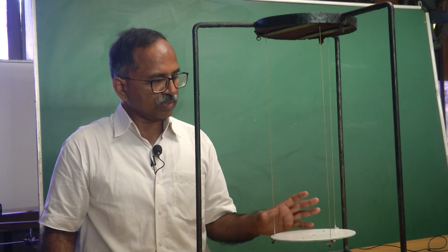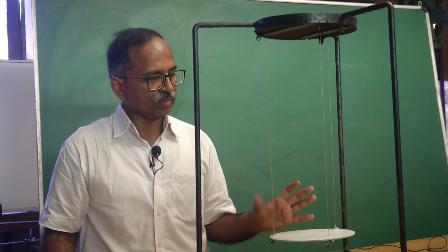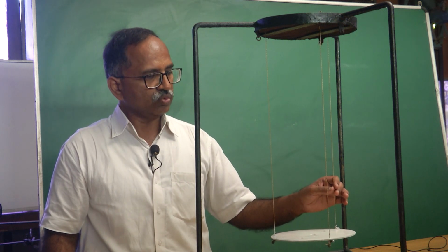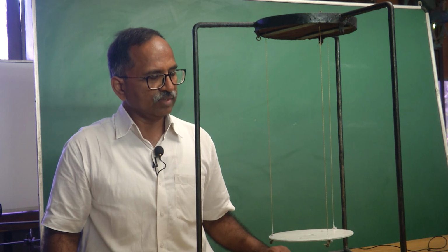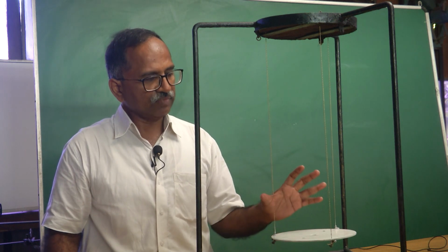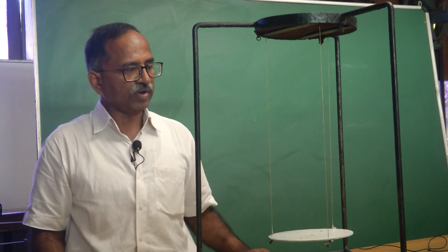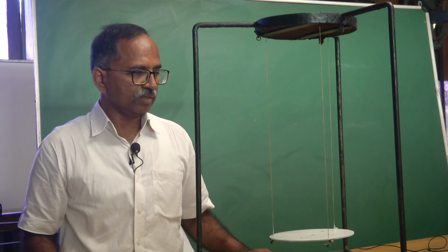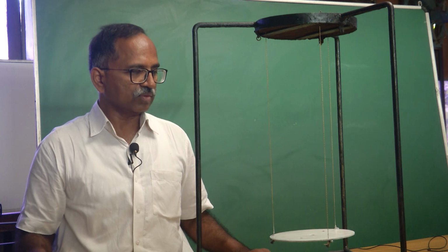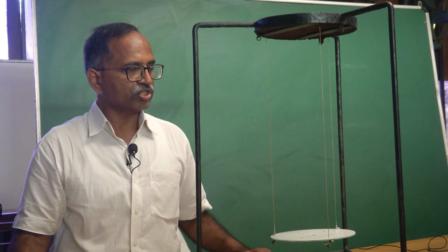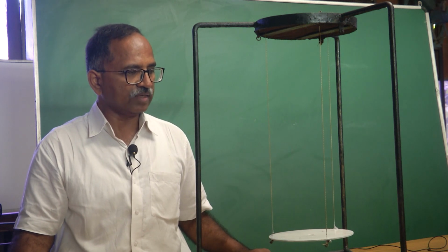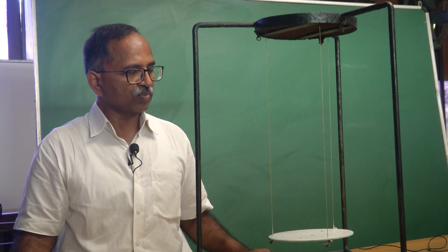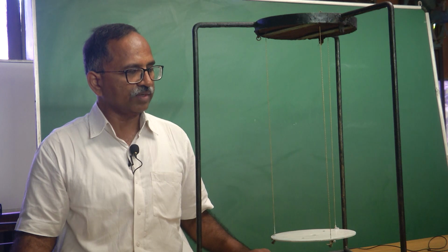Now, what is the purpose of this experiment? This trifilar pendulum is used to find the mass moment of inertia of any body whose shape and dimensions are not standard in that sense, so that the mass moment of inertia can be experimentally determined.